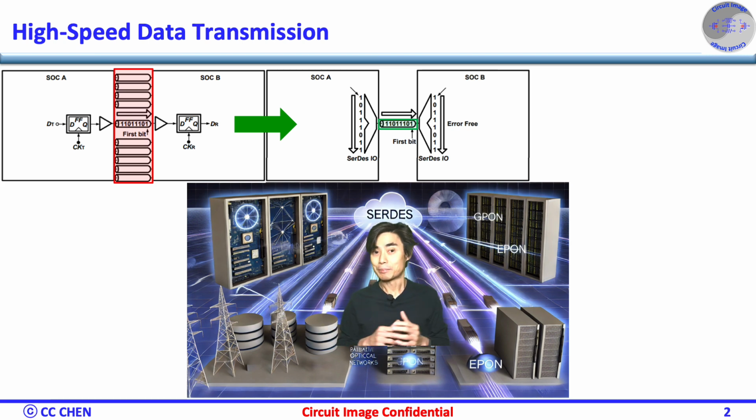In high-bandwidth applications, such as data centers or long-distance communication, PON technology, for example GPON and EPON, is used for delivering high-speed fiber optic connections. The SerDes interface supports these connections by converting data to a serial format optimized for optical transmission, enabling efficient data transport